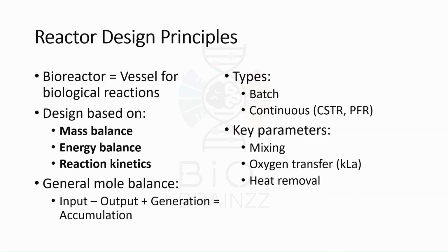A bioreactor is a vessel where biological reactions take place. It is designed based on mass balance, energy balance, and reaction kinetics. The main equation is input minus output plus generation equals accumulation. Important factors include mixing, oxygen transfer, and heat removal.